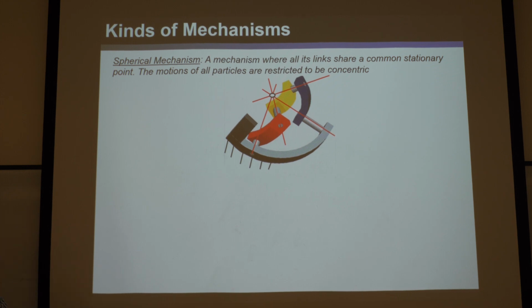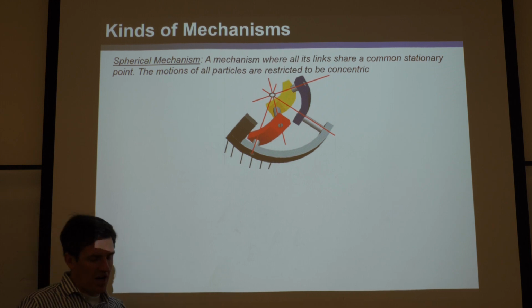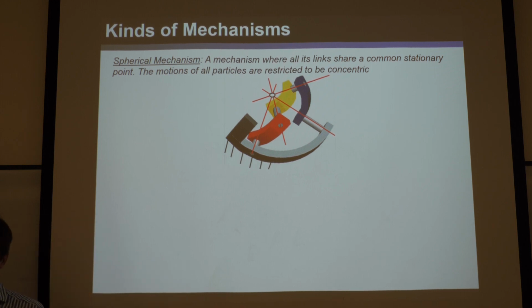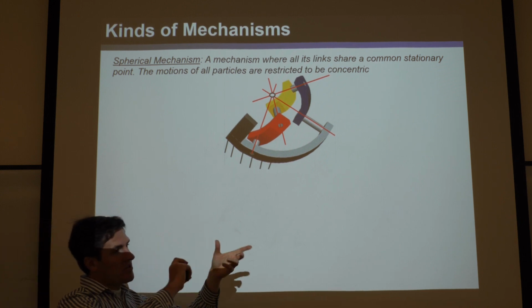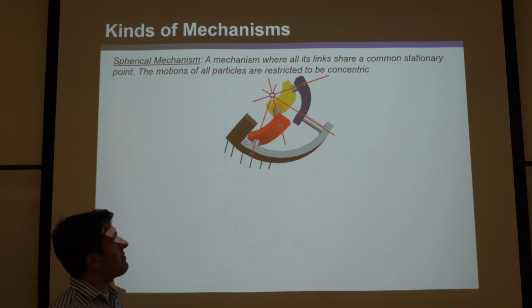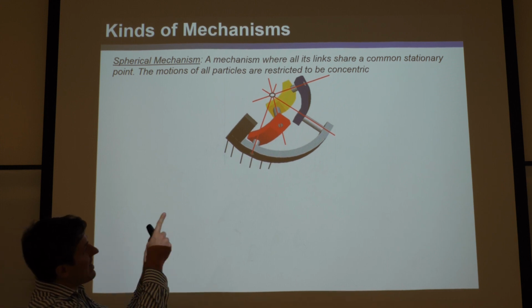Okay. The reason it's called a spherical mechanism is because those axes of rotation, those red axes I showed, always intersect at a common point, as you see there. You see that circled black outline dot that's white inside. That's where they all intersect. And no matter how those move, if you can visualize those red and yellow and blue rotating, those red axes may move, but they'll always intersect at the same point. Okay? And that point consequently won't move with respect to any of those other bodies.